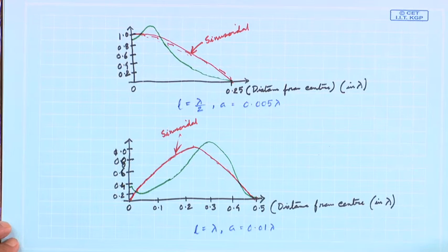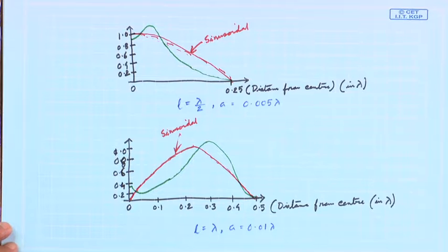Actually, earlier while discussing wire antennas for long dipoles, we said that the current distribution is approximately sinusoidal, because if we are feeding the dipole at the center, the conduction current should go to 0 at the two extremes and should be maximum at the feed point. But people have found out experimentally, and also by other techniques, that it is not exactly sinusoidal.